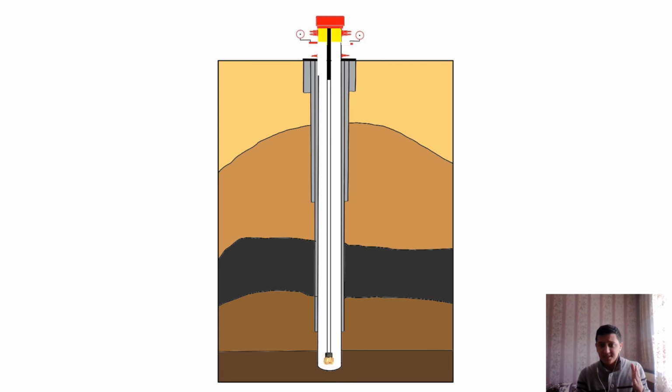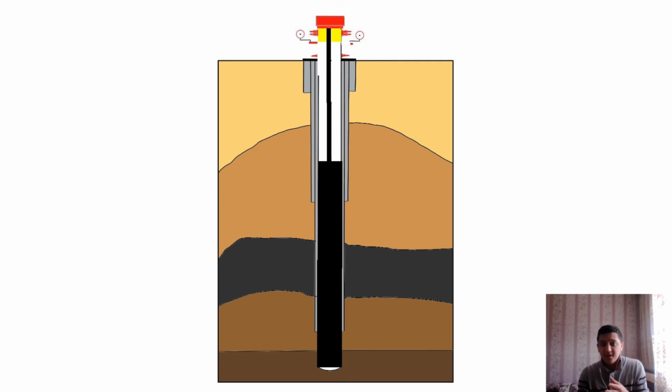As you can see here, first the normal mud is pumped and the gas is removed. As you can also see, the gas is expanding as it goes up. The circulating pressure drops, and the only job now is to replace the old mud with kill mud. Using old mud first gives time to calculate and make better kill mud.